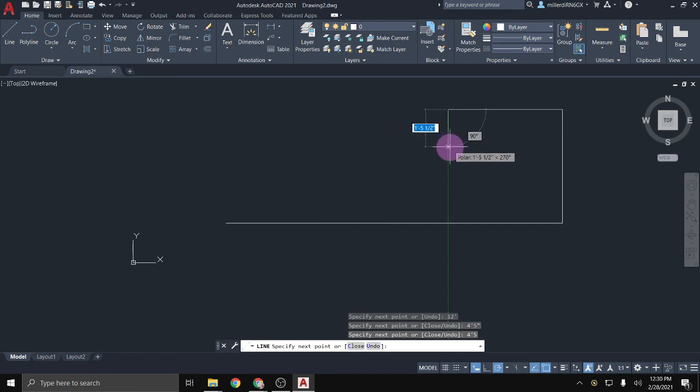If I have fractional inches that I need to put in, so I'll do 5 foot 7.5 inches, I would type in 5 foot 7-1/2. So this is not like SketchUp, in which that dash is going to be referred to as subtract. That means that it's 7.5. I could also do 7.5, and that would work out.